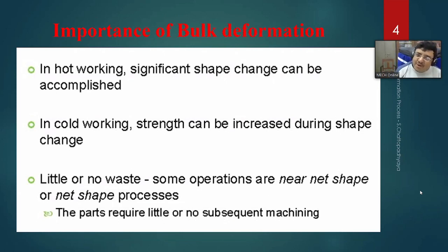What is the difference between cold working and hot working is that if you work beyond recrystallization, then it is hot working, and below it is cold working. Then recrystallization should occur at elevated temperature, and you know that it lies in the range of 0.3 to 0.5 of the melting point of that alloy in absolute Kelvin temperature. You cannot define it for every metal in general, but for each metal it is defined. So recrystallization is the phenomenon where you differentiate between cold working and hot working. Is that clear? Students, all 32 students, you should not forget about that.